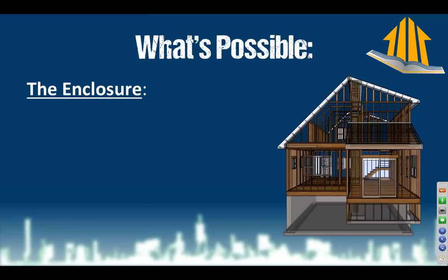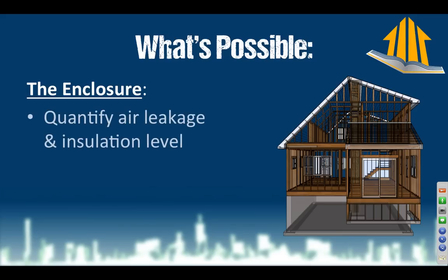So here's what's possible in the enclosure. Now, this is our renewal of vows. We're going to look forward in 2015 here. We're really excited about what's going on. The enclosure. Here's what I want. I want to quantify air leakage and the insulation levels everywhere in the house. And that has to do with just the enclosure. The insulation level in the floor between a living room and a bedroom doesn't matter because that's not part of the enclosure. The enclosure is everything between inside and outside.